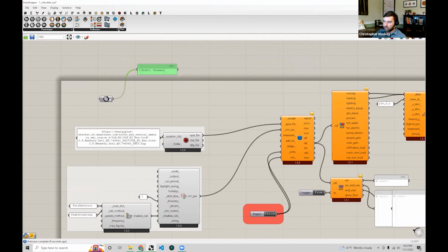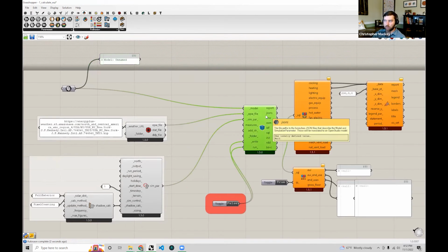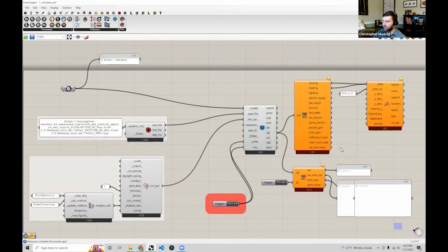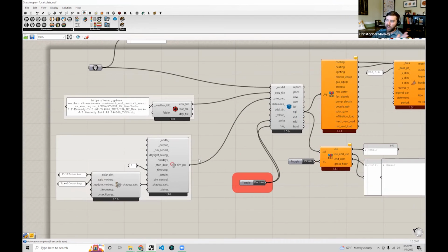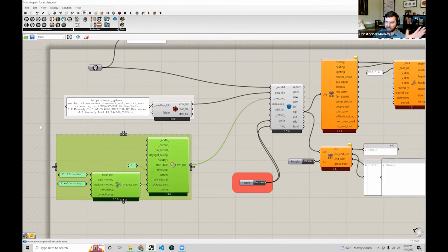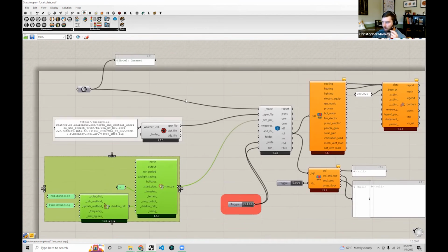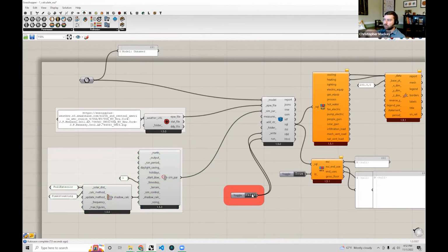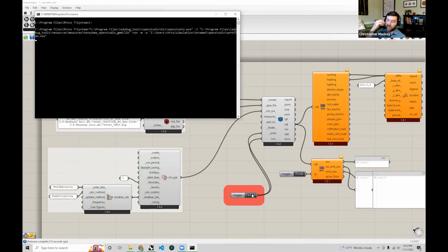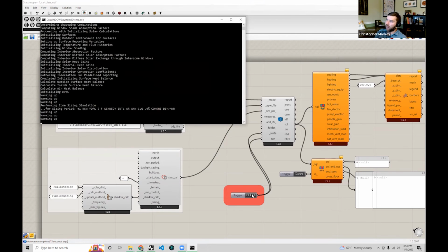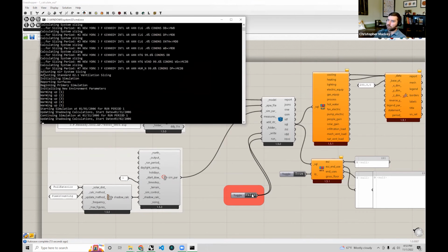So the nice thing about this is I can connect this up to my script that simulates the model in OpenStudio and EnergyPlus and pulls in these particular results that I care about, and uses my special simulation parameters that I know will be fast and quick to run this type of simulation. So I can set this true, and now I have a reusable Grasshopper script that I can use anytime I want to run an energy simulation on a specific Pollination model. All I have to do is get that model from the Rhino plugin, and the same script can be used multiple times.